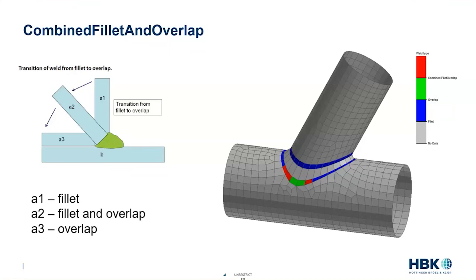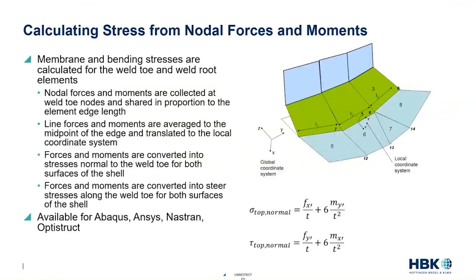The other thing that's going on is how we calculate stresses. And again, this comes back to this whole concept of structural stresses. Structural stresses allow us to calculate this damage measure that is relatively independent of the mesh. And this is an awfully wordy slide, but just take a look at the picture here where we have green elements that represent the welds. And we can see we have 2 sets of parent metal attached to it. We'll focus in on the parent metal at the bottom. So we have these elements here that are touching the weld toes of our weld elements.